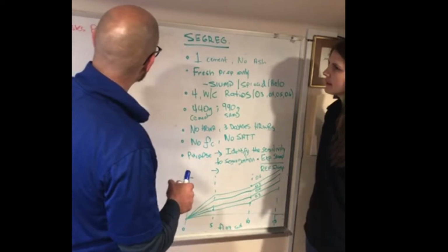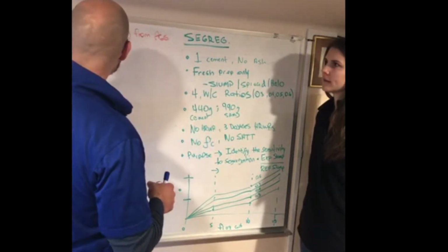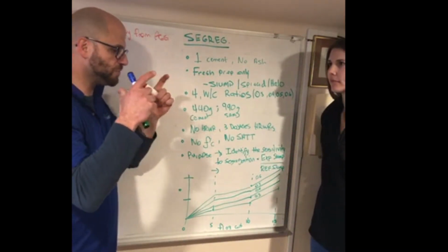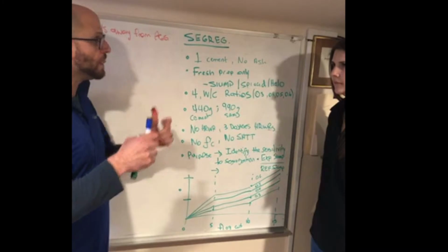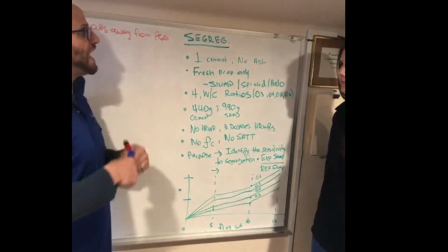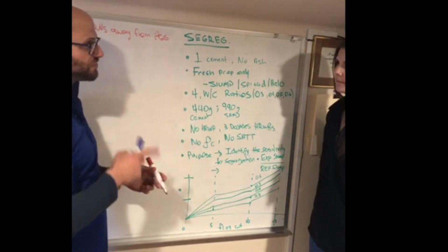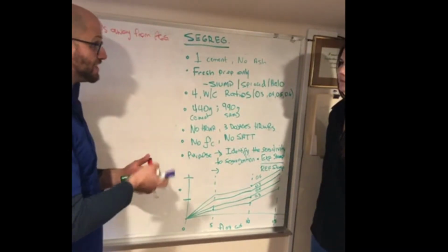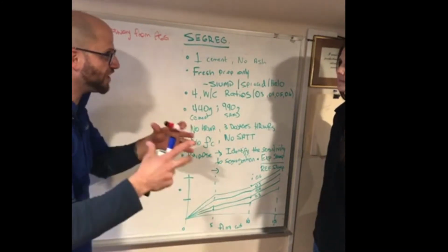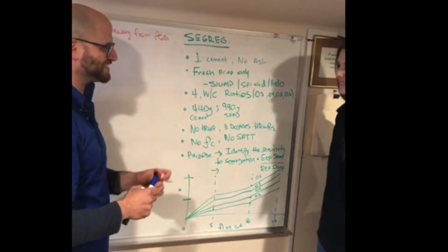Different than bleed water? Absolutely. That is still a response from the force of gravity, but now it's everything heavier in the concrete is segregating down, and excess water is bleeding to the surface. That's actually a definition from ACI CT 18, concrete terminology. I had to look it up for one of our committees. There was a big fight going on, and it was all based on that definition. It was pretty freaking awesome.